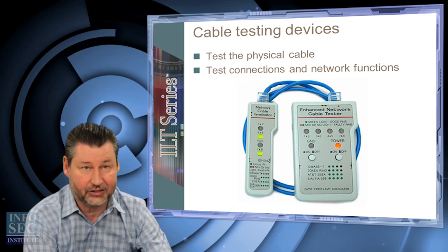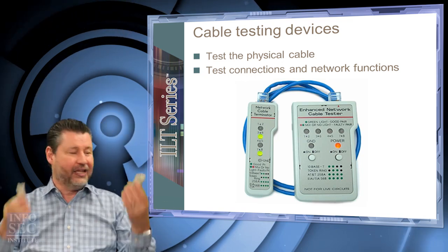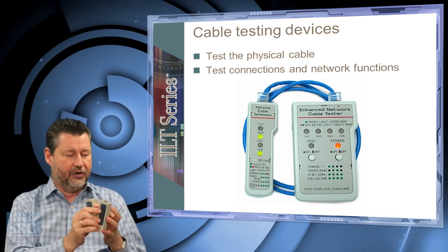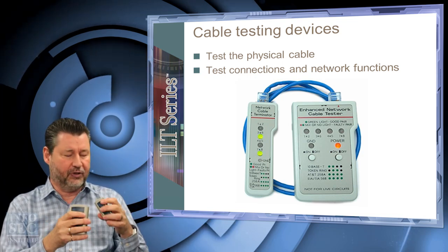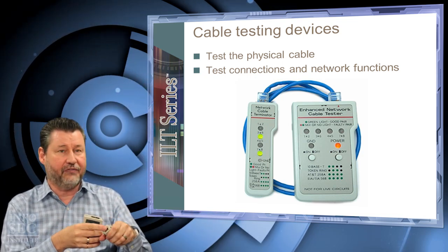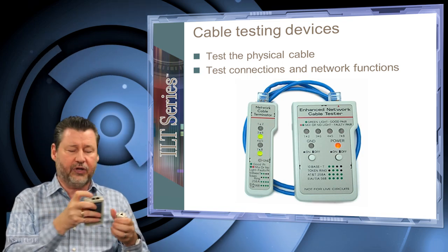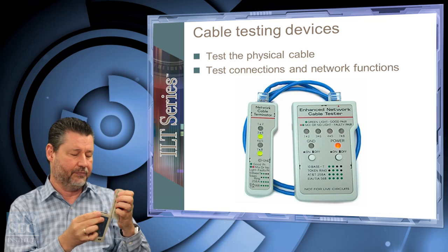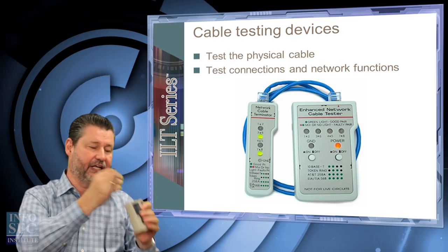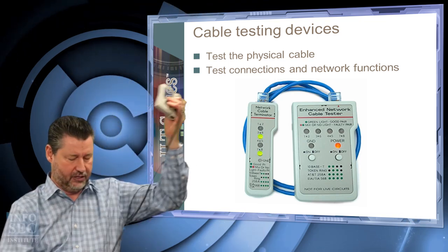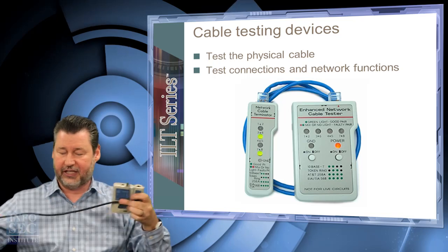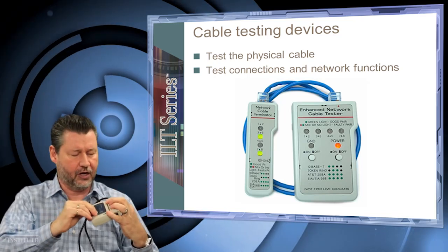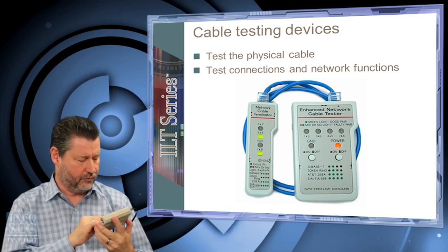There are cable testers. You see one there, here's one here. Use this for testing standard twisted pair cables. RJ45, RJ45. If I want to test a regular phone cable, RJ11, other side, RJ11. Now I just take this, plug it in, plug this into the other side, and usually these will be far apart. Turn it on, and what did I do?